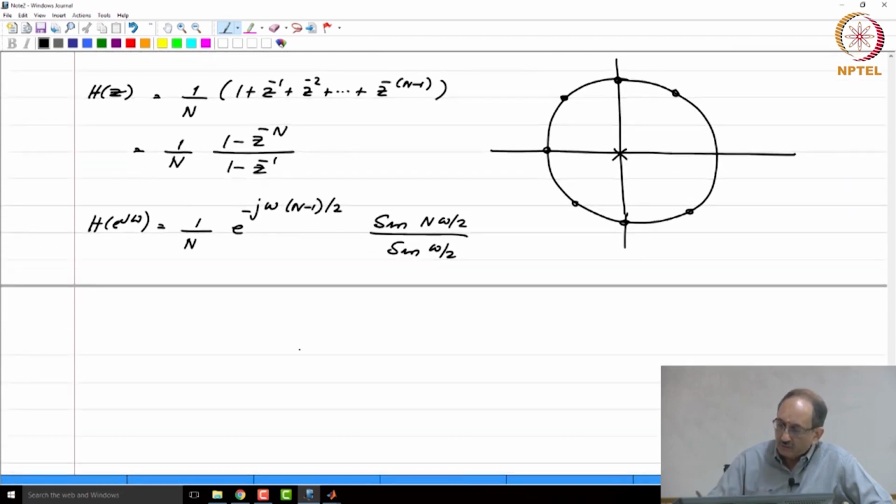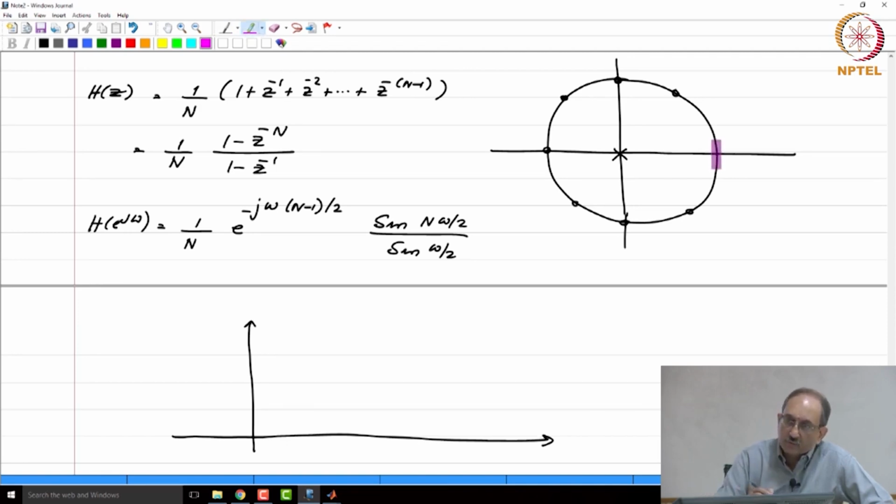And then remember we are looking at the magnitude frequency response, and we have been introduced to the geometric interpretation of the frequency response. Hence if you are on the unit circle here, you will have a certain value. Therefore, the response will have a certain value like this, and then from this point when you move across the unit circle, when you approach this zero, the response will fall down, and when you hit the first zero as shown here, the response will go to precisely 0.